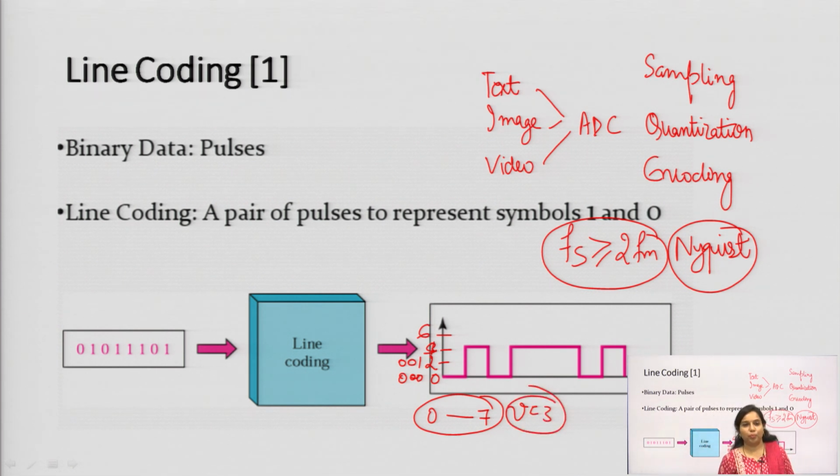If I am considering a 2 bit encoder, then 4 different options are available, that is 00, 01, 10, 11, meaning from -2 to +2, 4 different options are available for the amplitude level. So, this is the work of encoding, the number of bits I am going to consider. So, now after listening to this, you want to know where line coding comes into the picture.